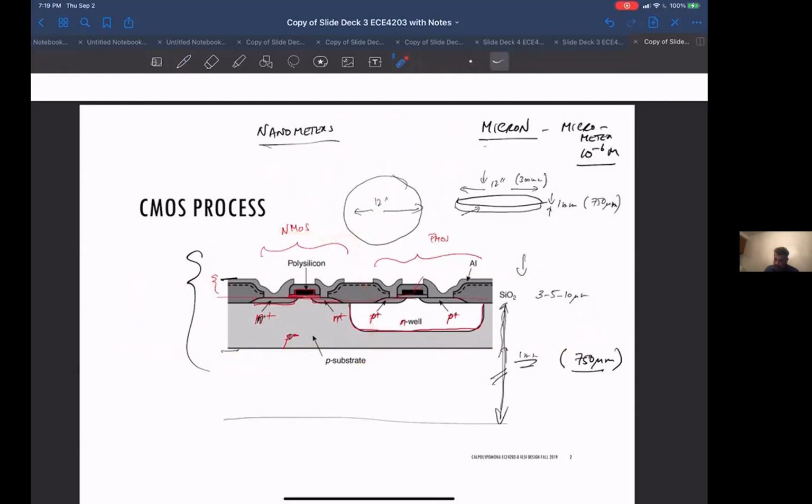So for example, in this NMOS transistor, our gate and oxide are sitting here, but instead of this whole area being N plus for the source drain contacts, the contacts are only on the very top surface. So the whole operation of the transistor is very narrowly close to the top surface. And the silicon wafer itself very typically ends up being a p-type substrate, so you can make the NMOS transistors right on the substrate. This is the p minus.